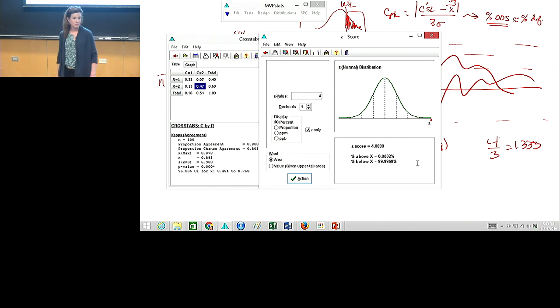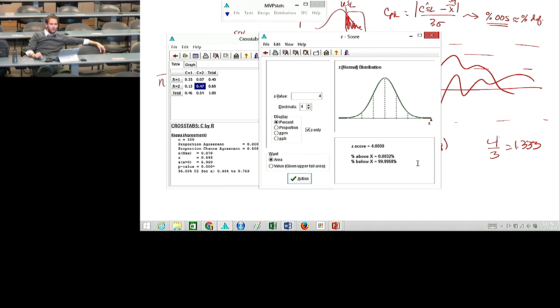Yes. Can we rewind a little bit? Yes. Capability. So since we have, in this example, equal subgroup sample sizes of 500 each, we can use an NP chart, right? You can use an NP chart. Yep. Okay. You can use an NP chart and then figure out what your proportion defective is on average.